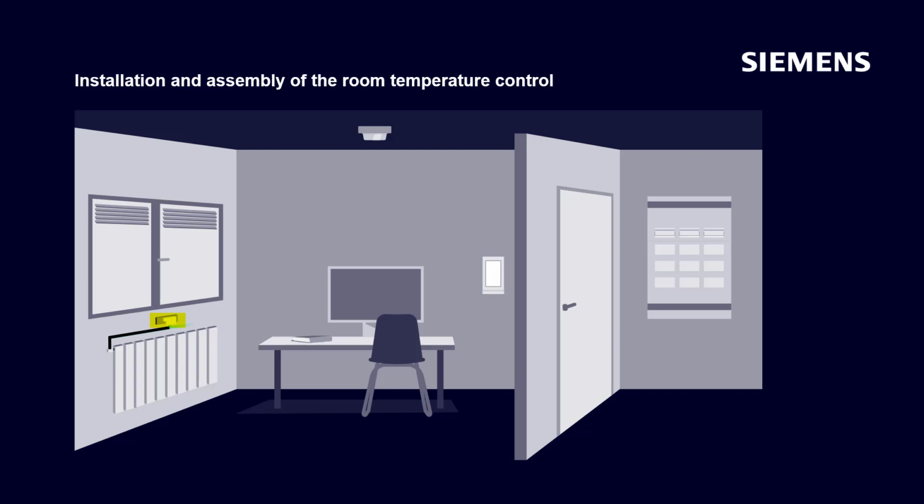This can be installed with the control module box AP118, which is available as an accessory for decentralized installation, in a dado trunking under the window. There, the thermal drive actuator is in the immediate vicinity of the thermal actuator, and there is a short wiring path for the load side connection. The individual components communicate via the green KNX bus line.